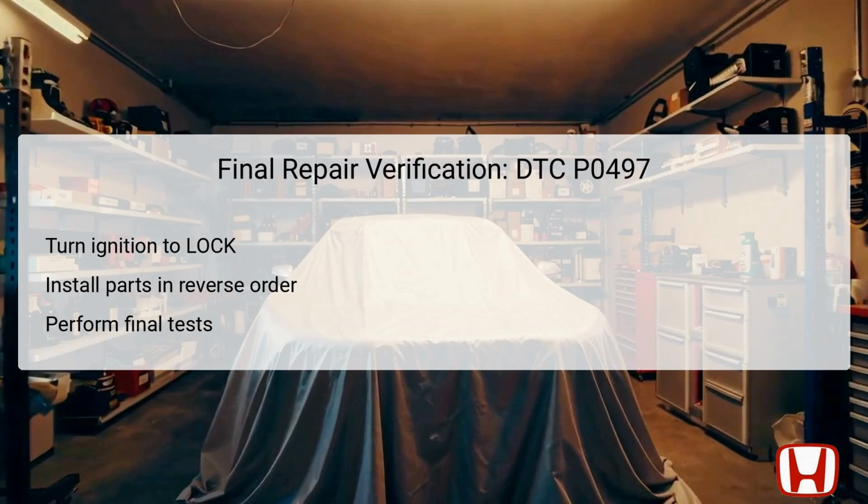Following the completion of all necessary repairs, it is crucial to verify that the actions taken have resolved the DTC P0497 issue effectively. Start by turning the ignition switch to lock 0. Then reinstall all components in the reverse order of removal during the diagnostic process. After everything is put back together, turn the ignition switch to the on position, second position, to power the vehicle's systems. Reset the powertrain control module, PCM, utilizing the HDS, which clears any previous fault codes stored in the system.